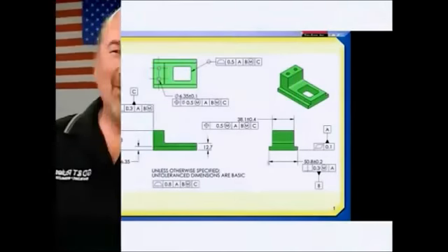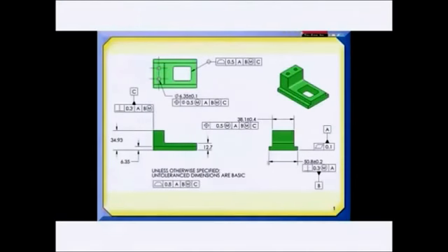Now, here's the tip. As I mentioned, datum feature shift, or displacement as the standard calls it, changes with part geometry. On this part, our primary datum feature is the bottom surface, and so in a setup I would set that against a plate, a very flat plate, to establish my primary or first datum plane.